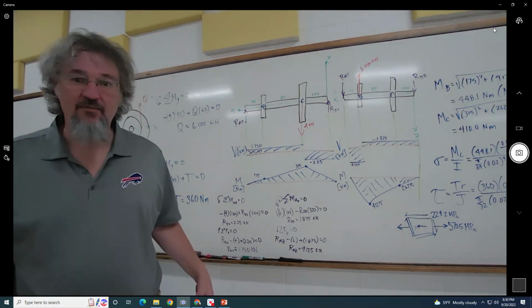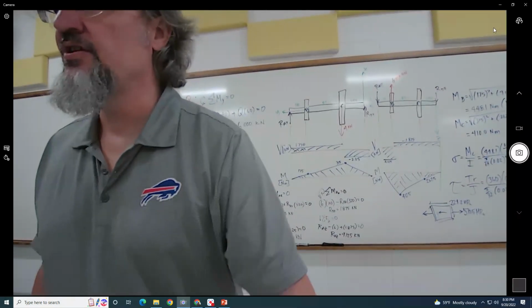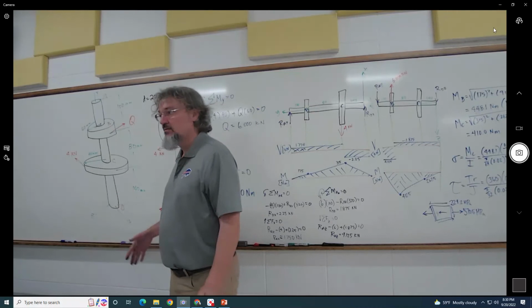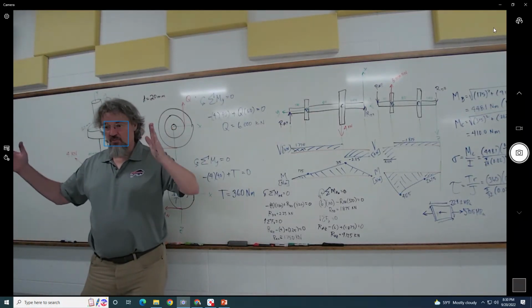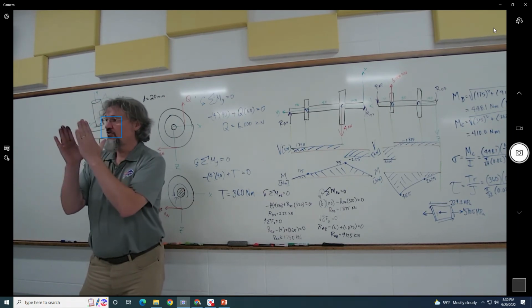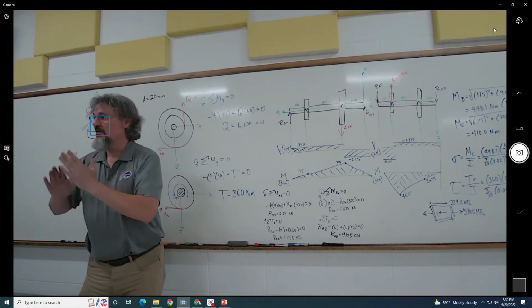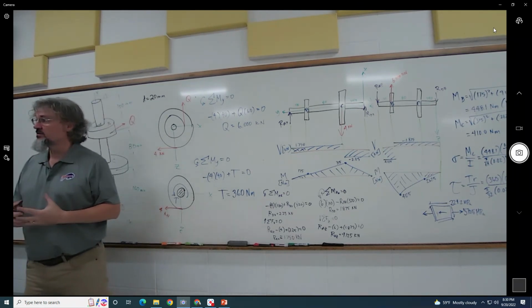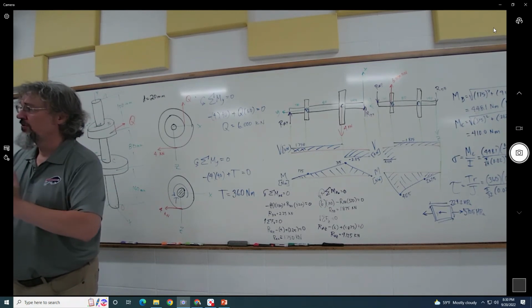I don't think you have many situations. It's really, well, I would say transverse is second cousin to direct shear. And so sometimes if the supports are very close to each other, then transverse becomes something that could be significant compared to the other stresses. Because when the supports get closer to each other, bending doesn't become as important because there's less of a moment happening.